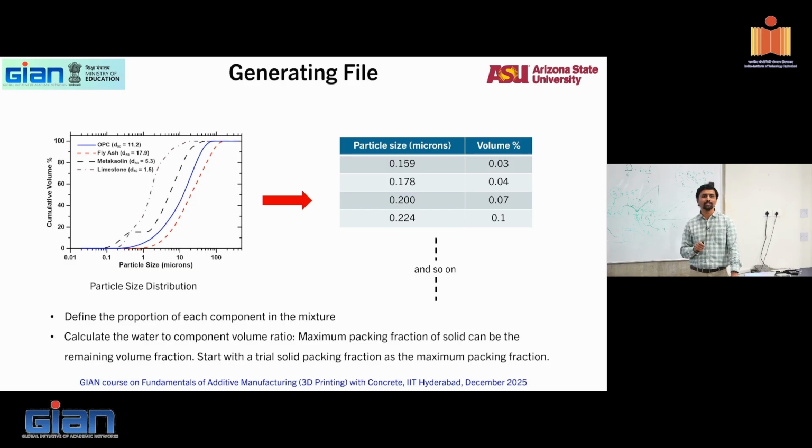For particle packing, it does not matter to distinguish between those particles. But if we have to use it further in hydration, we need to know which particle is what, because we can't ask limestone to hydrate like cement particles. For those reasons, we have it distinguished in the system. As a general start, we'll see it in terms of distinguished particles, so that later, when we have the hydration, you at least know how to reach the microstructure and start the hydration scheme.